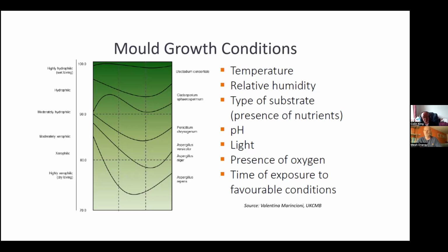But the main thing is, when you put these brick creams in, the clay bricks that you apply them to are not really the issue. The issue is the lime, because lime is very porous, clay bricks not so much. And the moisture content difference, when you've got a clay brick, it's quite normal for it to have 6% moisture content by volume and still be dry.